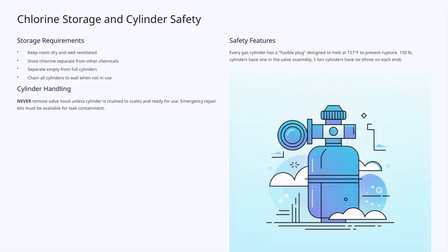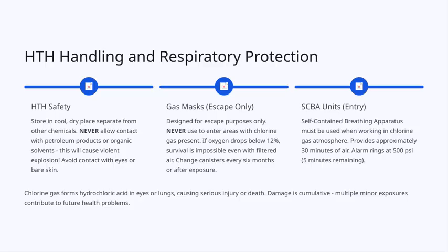Let's talk about handling and respiratory protection when working with HTH. First, it's crucial to store HTH in a cool, dry place, separate from other chemicals to prevent any unwanted reactions. Remember, never allow contact with petroleum products or organic solvents because that can cause a violent explosion, which is extremely dangerous. Always avoid contact with your eyes or bare skin to prevent burns or irritation.